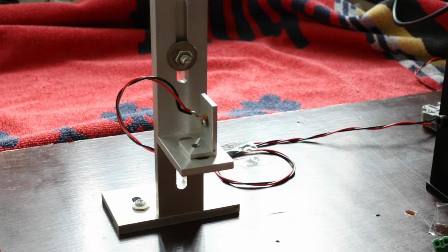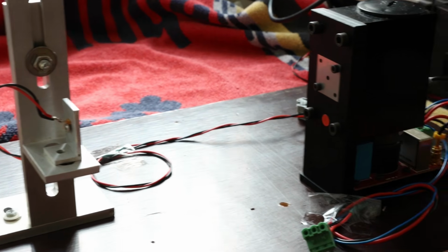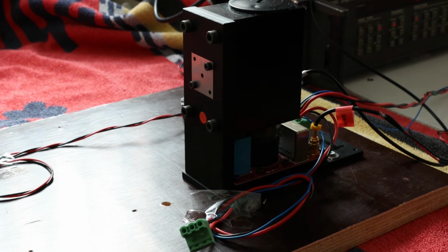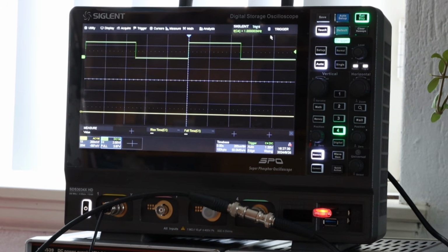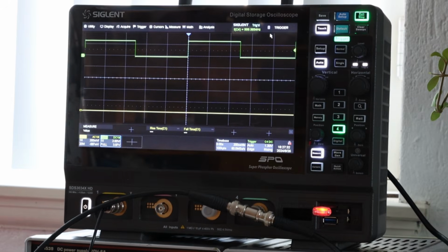And this very dim light source is placed at a distance of 200mm from the photomultiplier entrance without any lenses or focusing, just a small pinhole. I connected the light source to a function generator which allowed for modulating the light between on and off with a frequency of 1 kHz, and this is very useful because it allows us to directly compare the photomultiplier signal with light and no light being present.